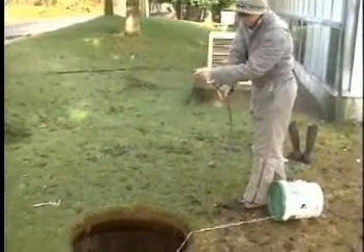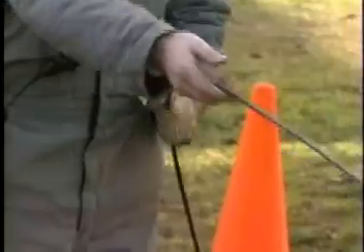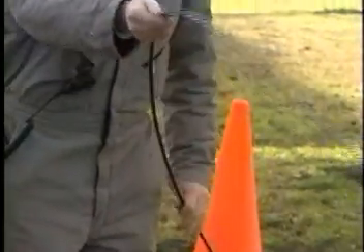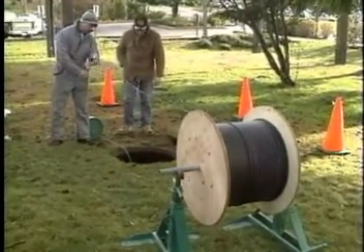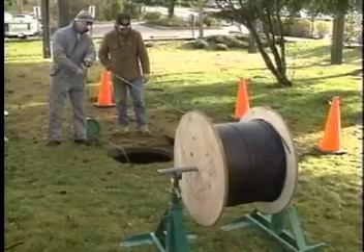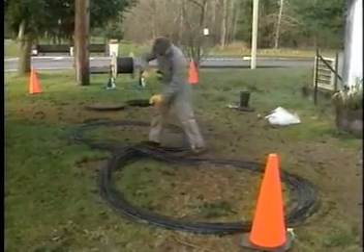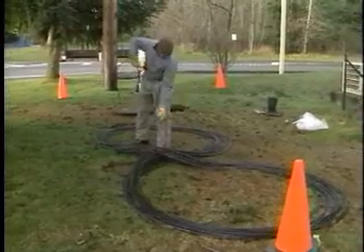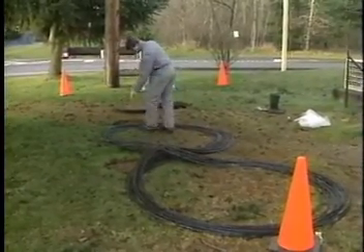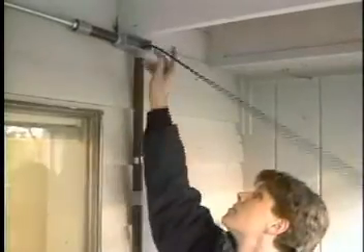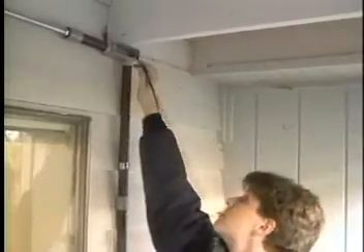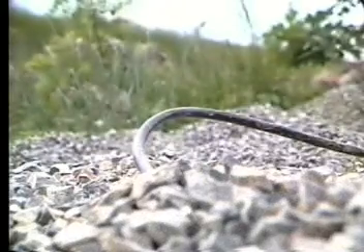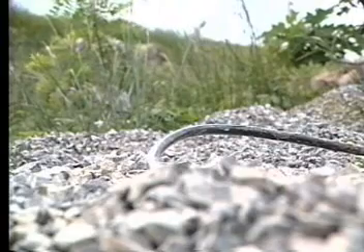A reel of fiber optic cable located at a manhole near the center of the fiber span feeds cable into the manhole towards the existing hub. The fiber distance from the manhole to the buildings is calculated, leaving plenty of excess cable for slack, and that amount is reeled off and placed in a figure-8 pattern on the ground. This technique protects the cable from excessive bend radius and twisting. The end of the cable is then connected to the newly installed pulling line and pulled through to the remote building. The cable must be protected from vehicular and pedestrian traffic while on the ground.